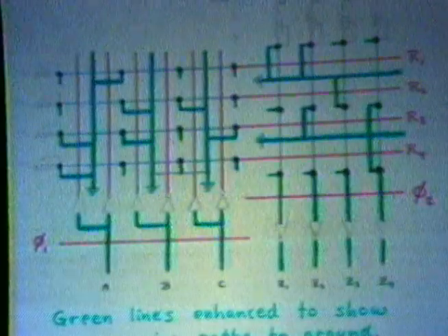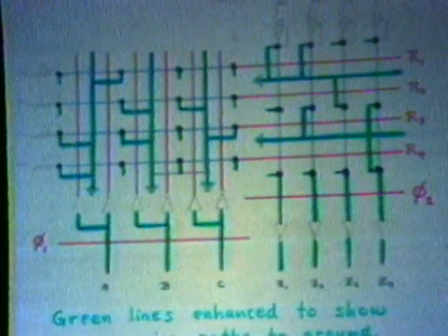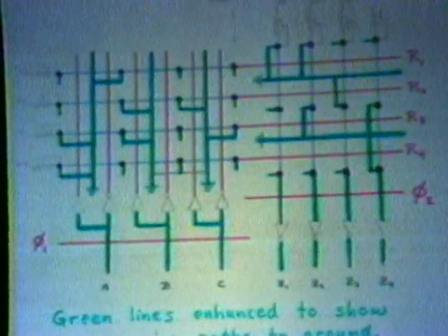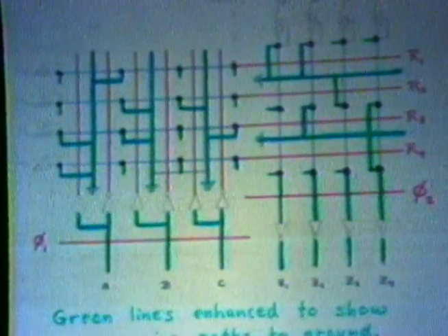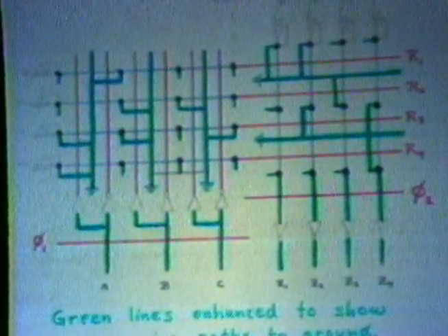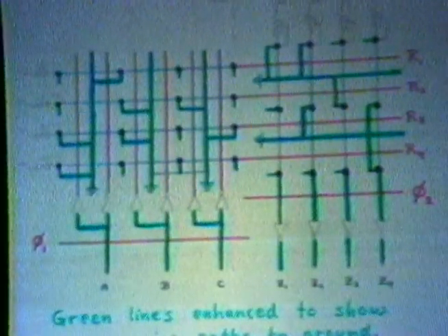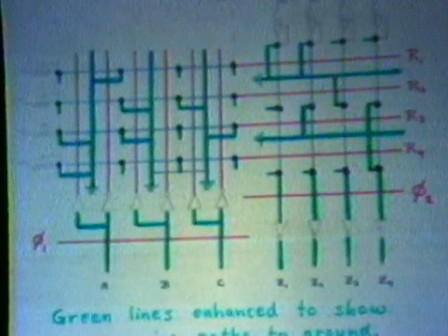So the left half of this structure, the AND plane, has vertical lines representing all the inputs and their complements. Each horizontal line in this structure corresponds to one of the NOR gates of what we call the AND plane. That's the first NOR plane. Those gates are sort of distributed. I mentioned here, can you find the gates?